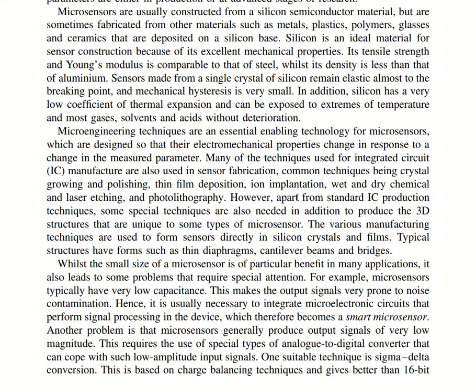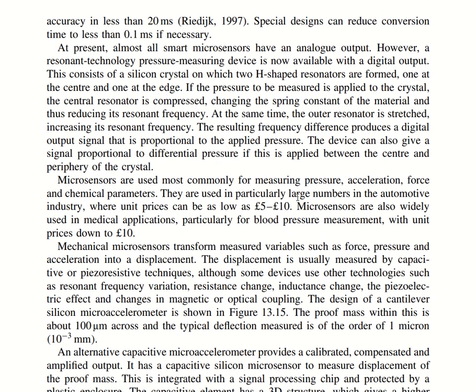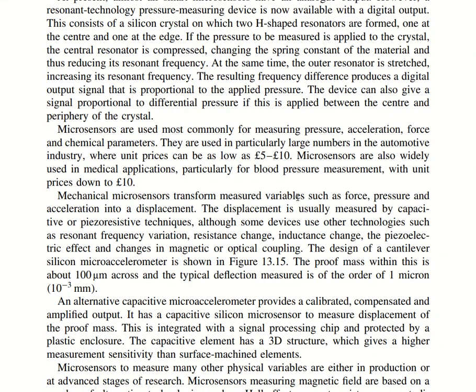This is based on the charge balancing technique and gives better than 16-bit accuracy in less than 20 milliseconds, right? So special design can reduce conversion time to less than 0.1 microsecond if necessary.